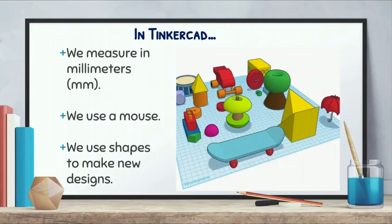While Tinkercad offers the ability to measure in inches, we always measure in millimeters, the default option, simply because it makes the transition from software to hardware, the 3D printers, so much easier. Our slicing software, which takes our designs from computer to printer, measures in millimeters, so it makes more sense to keep things consistent. Again, do what you think is best for your students.